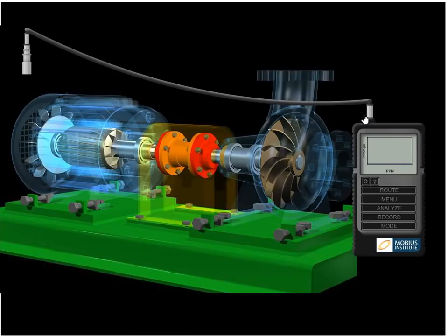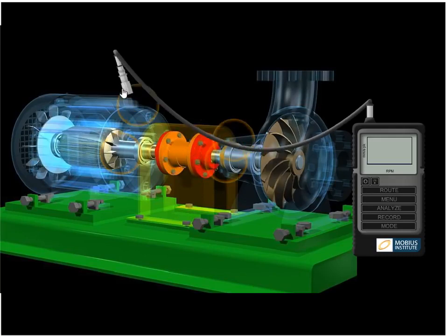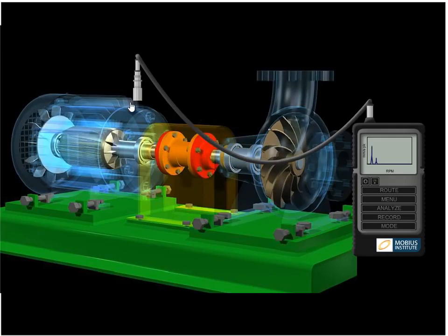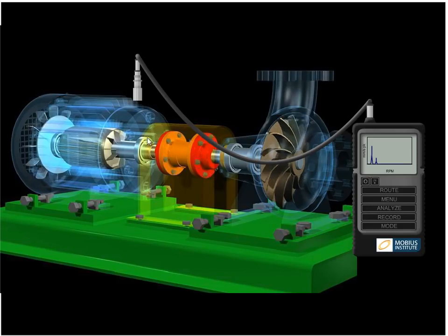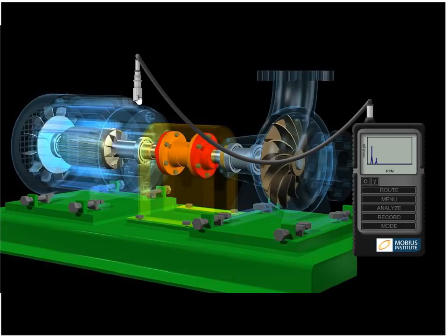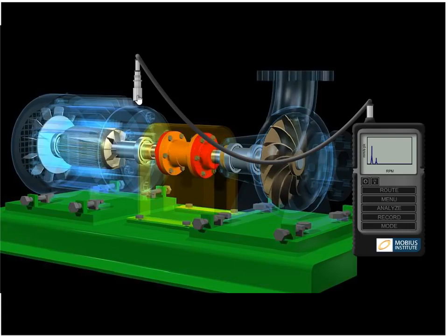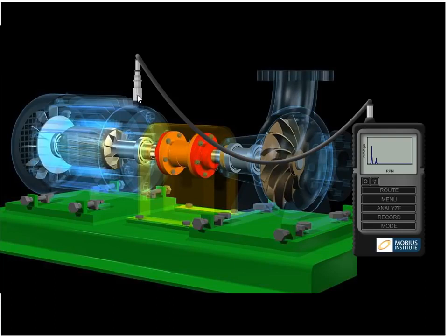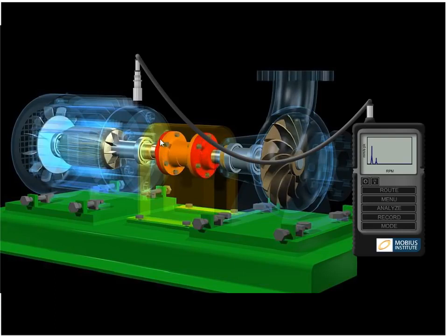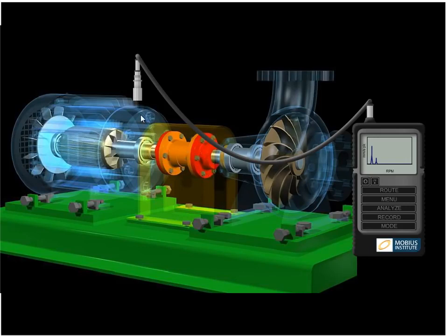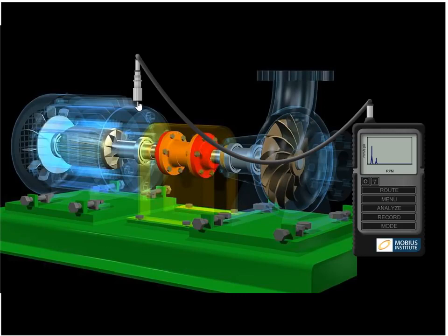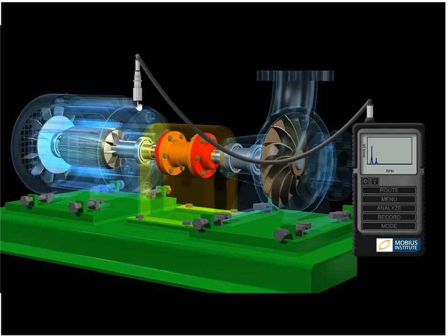Okay, so the way we do this is, as you've just seen, we can put the vibration sensor up there on the bearing, and all the vibration is transmitted through the machine itself up to that point. The sensor has to be mounted properly. That is very important, so that all those high and low frequencies get up into that sensor. But the fact is, when we mount it up on top, that is sensitive to the vertical motion.